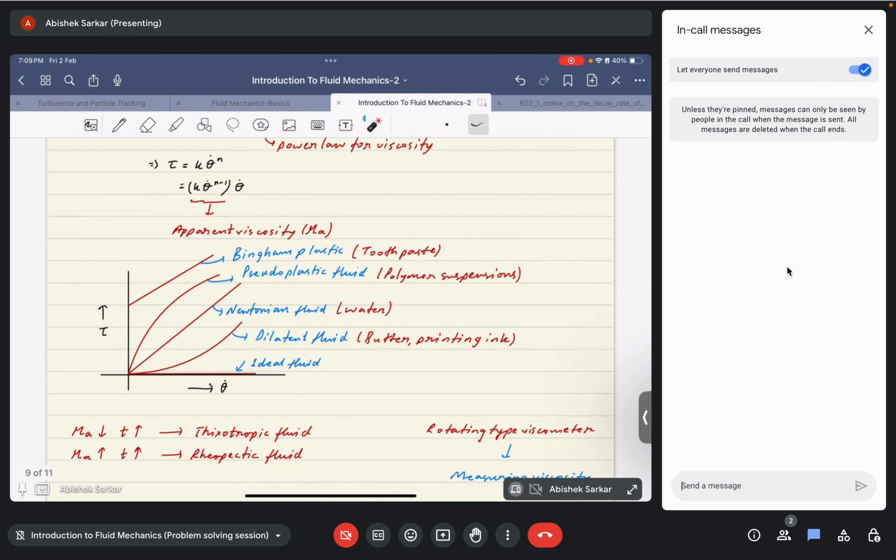So there are different types of fluids that come into the picture when we discuss Newtonian and non-Newtonian fluids. In the shear stress and strain rate curve, the Newtonian fluid would be a straight line, where the shear stress is proportional to the shear strain rate. But there can also be other types of fluids such as ideal fluid, dilatant fluid, pseudoplastic fluid, and Bingham plastic fluid. I don't feel that I need to discuss it again. If you're interested, you can read about them in different books, or just revisit the lectures.